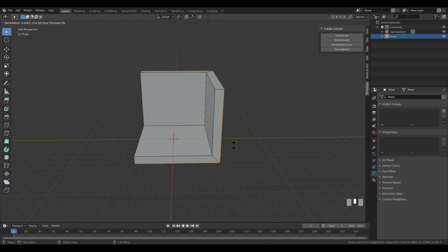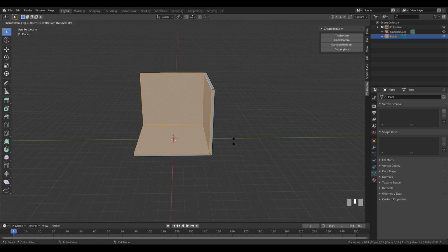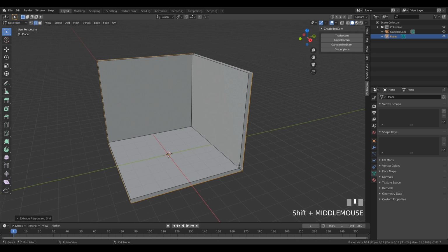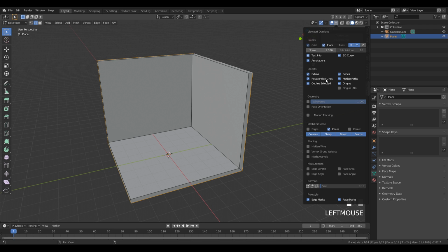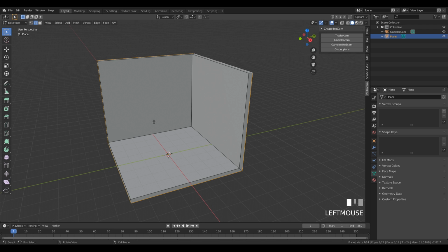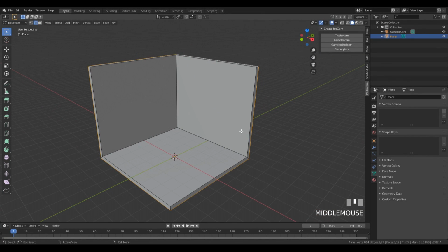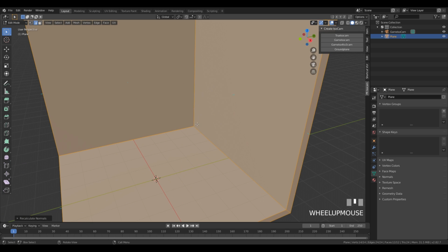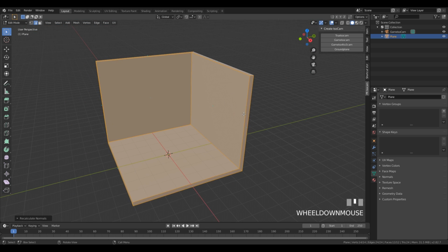And we can enable S for even thickness, and right now we can enter something like minus 0.3. Okay, and don't forget to check normals if you do something like that, because we extrude it in a negative value, so maybe our normals are not working correctly, because you can see. So if you press A to select all and Shift N, we flip the normals and they're now pointing correctly outside of these faces. So that's always nice to remember.